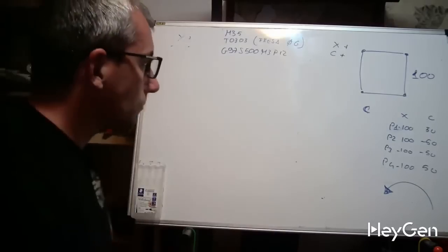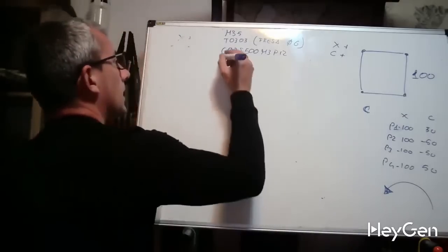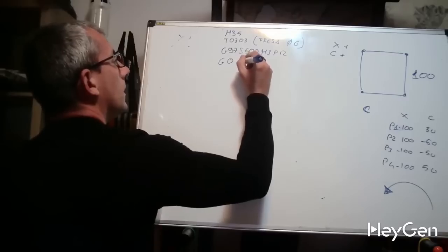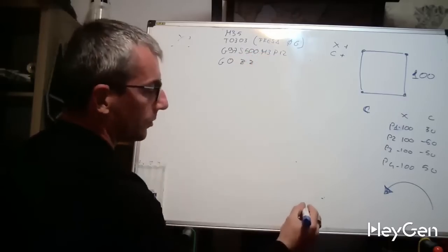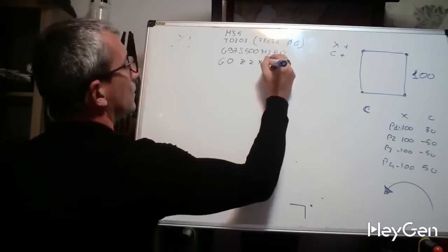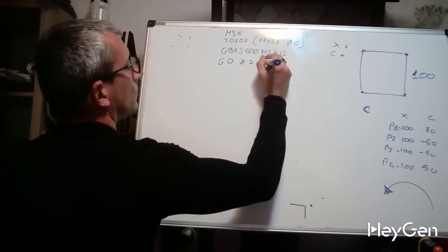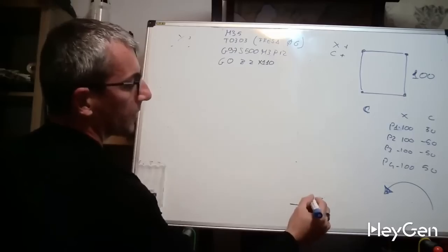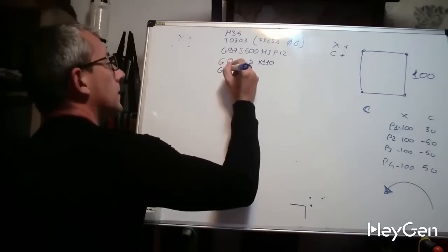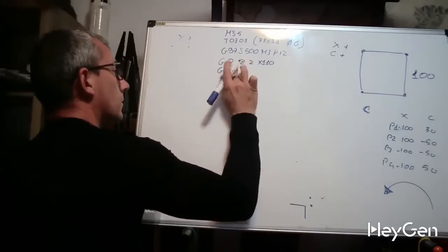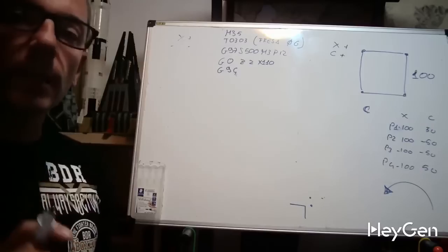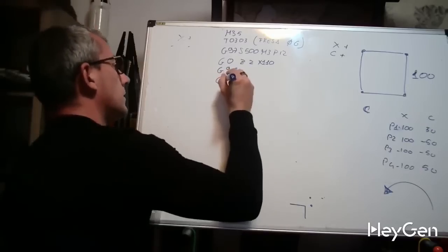Then we swiftly and efficiently move to G0, Z2, because obviously we need to mill a square, so we move there. Here, X110, so higher than the frame that we need to mill, we enter. If we want to work in millimeters per minute, the G94. And this is the moment to enter, in a separate block, without any other code, the G112.